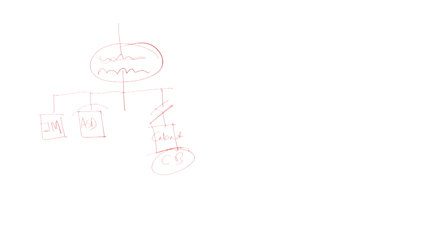Then this adjustable speed drive will produce some amount of 5th, 7th, 11th and 13th harmonics, and so on. It may be the 5th harmonic, quite a dominating harmonic.